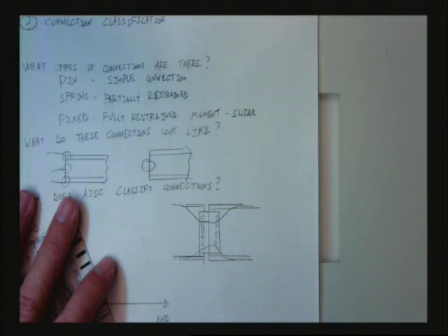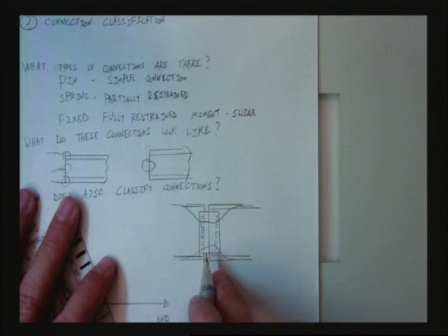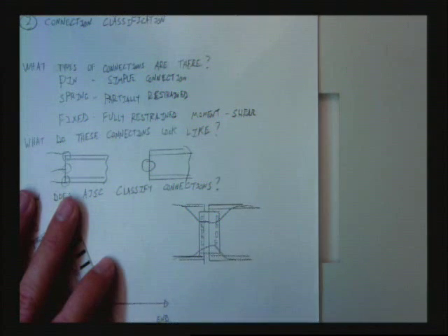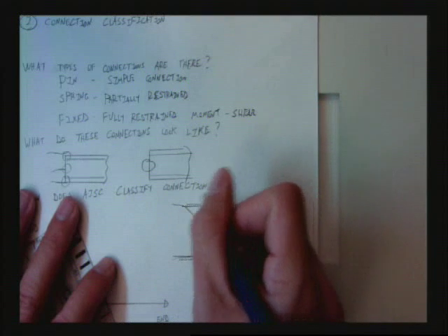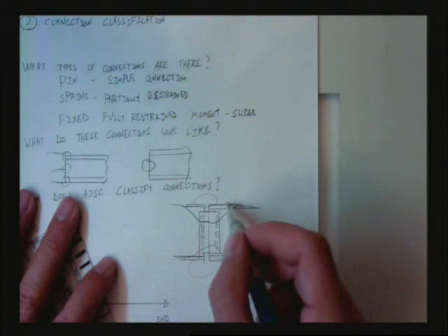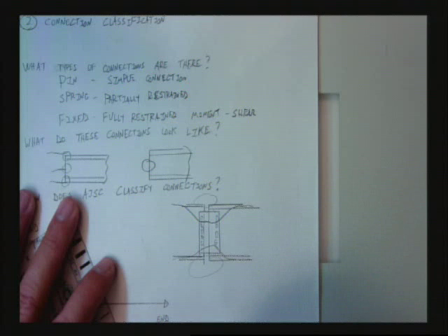And if you wanted to, because if you talk to those guys and if you listen really close, those WW Steel people, they would say things like, well, we would usually do this with a fully restrained or a full penetration weld, but we beefed up the plates and we got away with doing it with a partial penetration weld. They're doing those things to try to save money. And if I can keep from putting a plate here and a plate here and making that connection, I can save money. Is everyone with me on that?